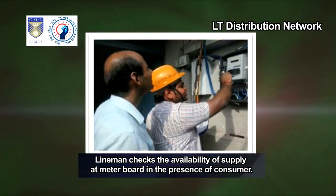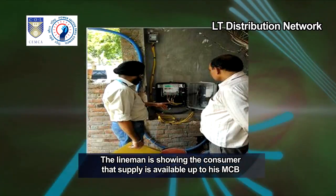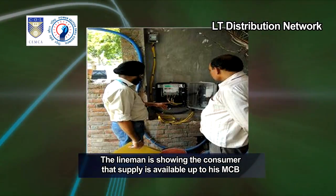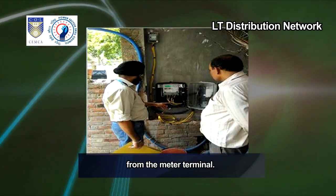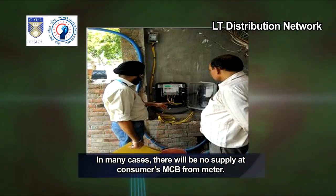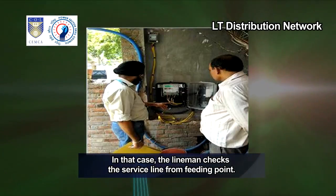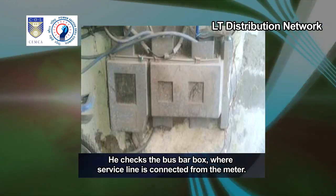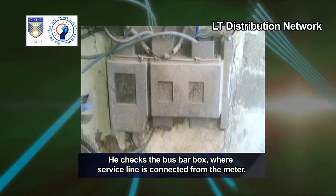Lineman checks the availability of supply at meter board in the presence of consumer. The lineman is showing the consumer that supply is available up to his MCB from the meter terminal. In many cases, there will be no supply at consumer's MCB from meter. In that case, the lineman checks the service line from feeding point. He checks the bus bar box, where service line is connected from the meter.